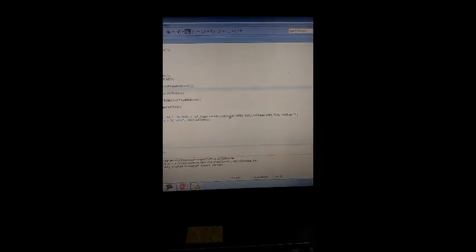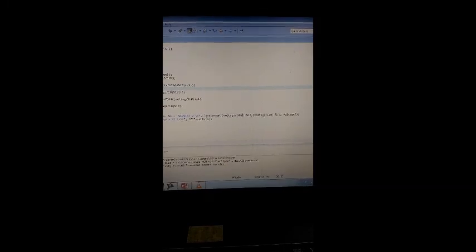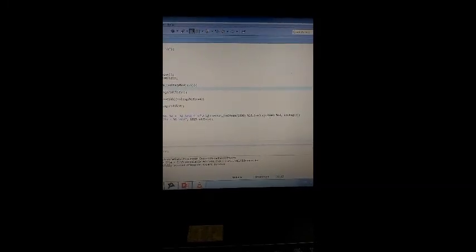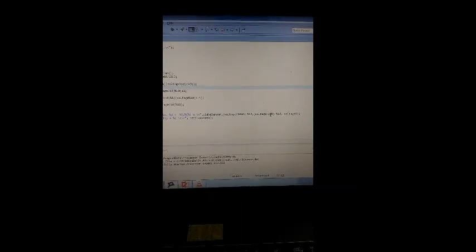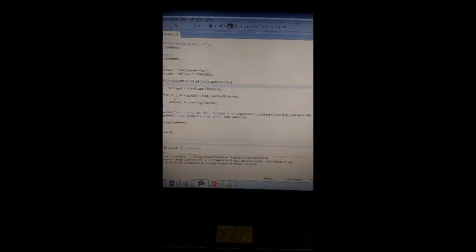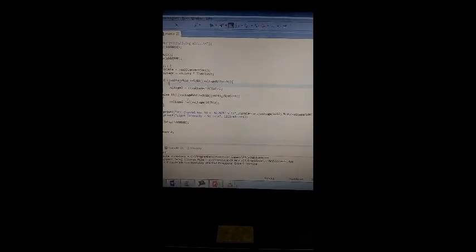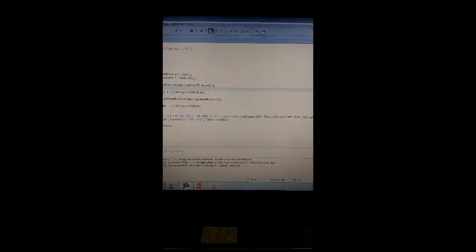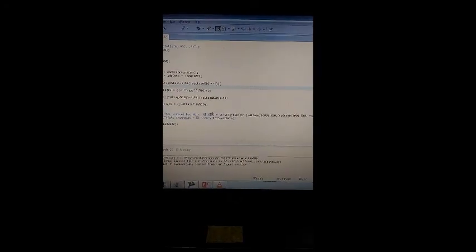And the only changes made were, instead of voltage divided by 100 for the first one, we divide by 1000, and the first digit right after the decimal will be voltage divided by 100. And last but not least, the voltage 2 that we get from this if else statement, we straight away put it as our final digit for the decimal place.